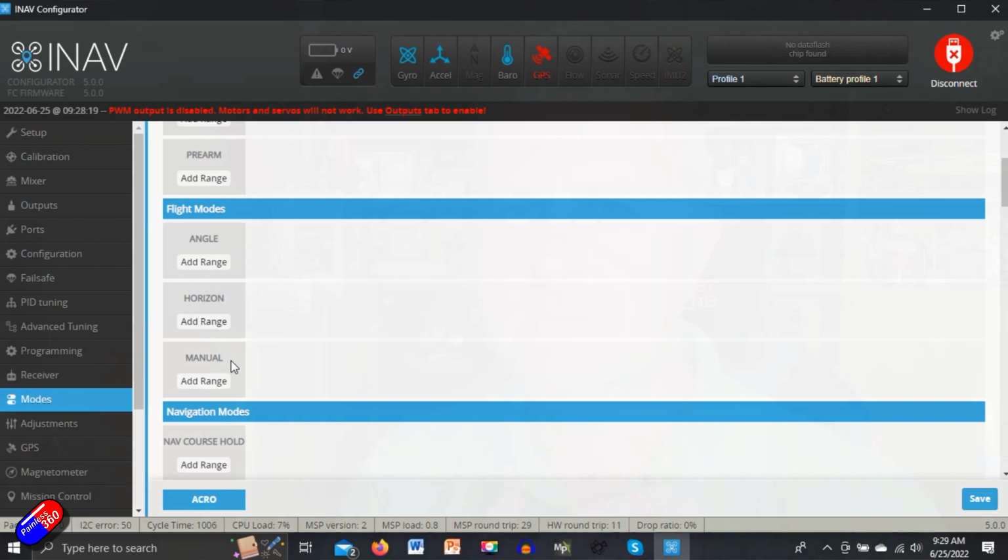Horizon is one of my favorite modes, particularly when you initially launch it. It means that the plane, if you have an issue, will continue to fly straight and level. So with all these, definitely make sure that things like failsafe is set up and working flawlessly. Again, see the other videos, because with something like Horizon set, if it isn't set to come back to you in the event of a failsafe, the plane will just keep going until the battery gives up.